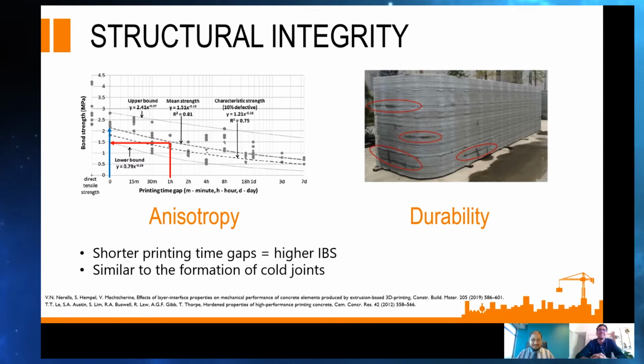Maybe a quick question now in terms of the mix design. Is there a specific concrete strength that you work towards, or can you get varied concrete strengths? What are we looking at in terms of your concrete strength? Yes, absolutely. These mixes are completely customizable. As with normal concrete mixtures, you have a target strength which you design for, and then ultimately try and reach it. However, in general, you'll see mixtures from about 25 MPa all the way up to 70 MPa due to these sort of more mortar or grout-like constituents that we use and the particle sizes.